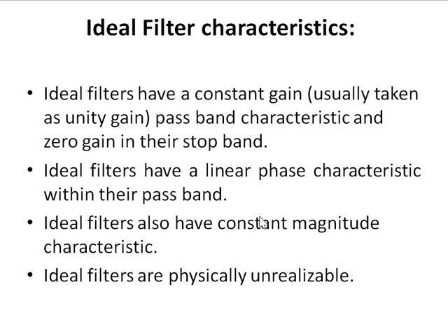And another one is related to the phase response, that is ideal filters have linear phase characteristics within their pass band. And ideal filters also have constant magnitude characteristic. So these 2 points are related to the topic distortionless transmission through a system. In that we discussed about this topic.